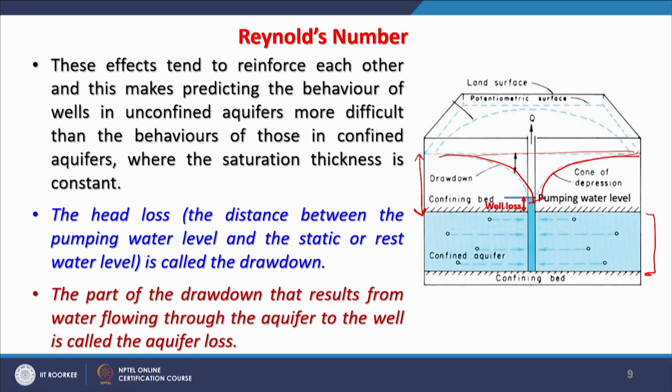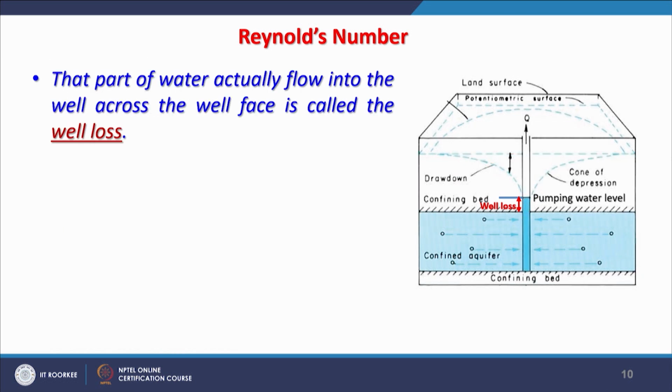So, as mentioned earlier in previous videos, the withdrawal of water has to be done very judiciously, in an optimum manner, so that the drawdown does not go very deep, and there should be some time so that it settles, the drawdown disappears, and then you start withdrawing water again. That is the best practice that should be followed, not continuously withdrawing water, otherwise there will be problems in the well.